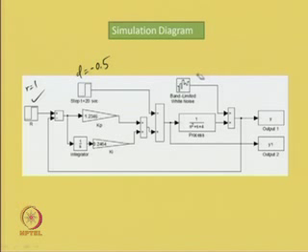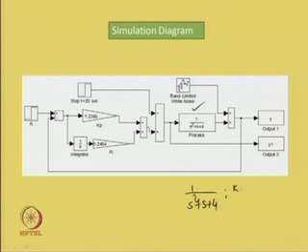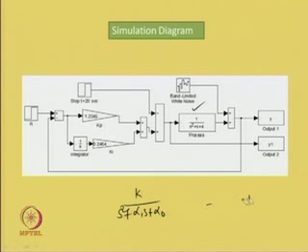Let us look at the controller dynamics of the process and so on. Now, the process dynamics is shown over here, which is given as 1 upon s square plus s plus 4. This is obtained when we assume the specified values k equal to 1, alpha 1 equal to 1 and alpha 0 equal to 4, because the standard form of the all pole second order transfer function is k upon s square plus alpha 1 s plus alpha 0.